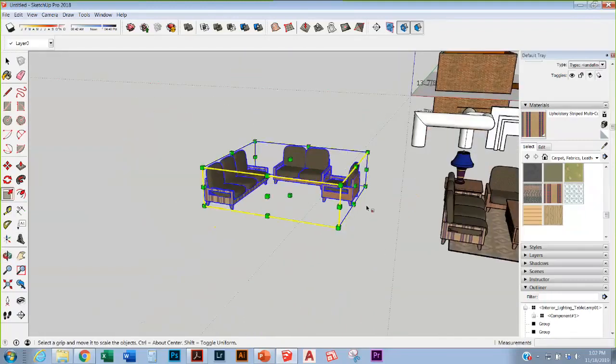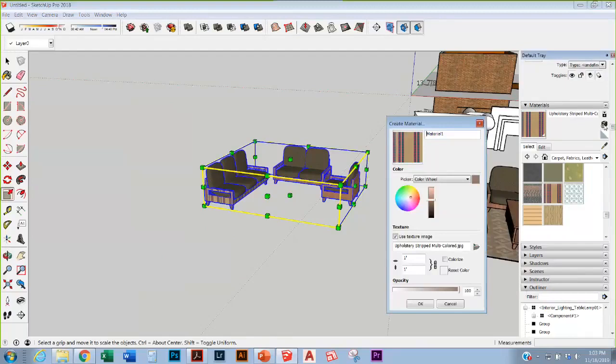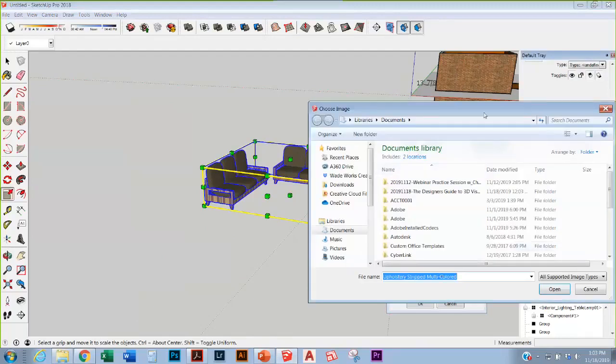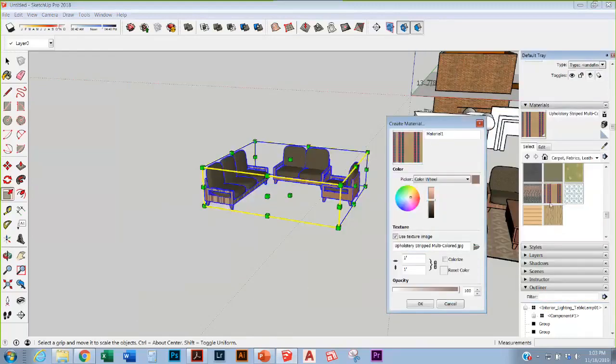Control Z, which is undo, is probably your most helpful tool that exists. Can we match or use a material from online? For example, a backsplash tile? Yes, absolutely. Say you have a picture, you would just upload it right here in your gallery. You would add a material and upload it right here. You would just grab this and select your file, and it would upload and sit right here in your gallery, and then you could texturize any surface that you'd like.